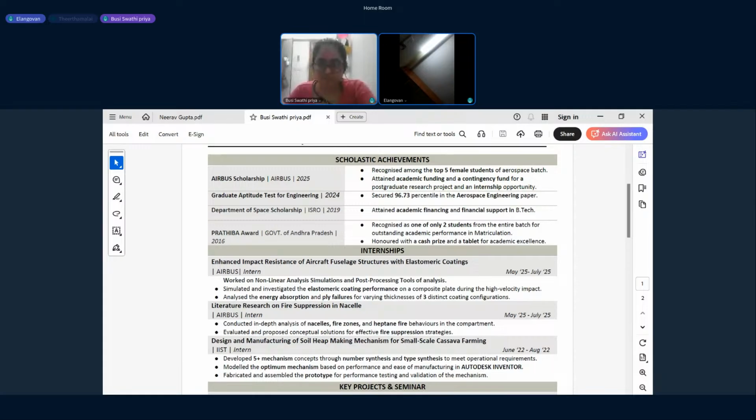If the Mach number is above 1, which means the velocity is greater than the speed of sound, it is called supersonic, sir. Okay, in supersonic, what is happening which is not there in subsonic flow? The downstream information cannot reach upstream, and there is a formation of shocks which are not there in subsonic flows.